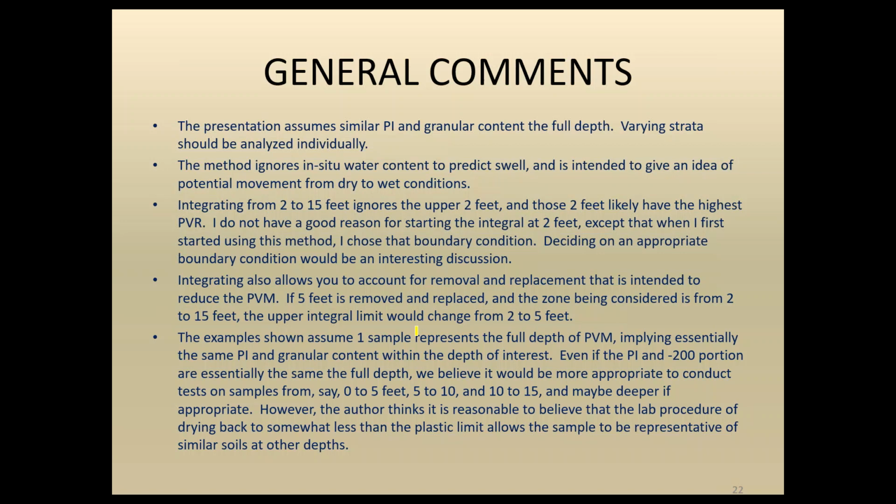So some general comments. We've, of course, assumed similar PI and granular content to full depth. So if you've got varying strata, they should be analyzed individually. The method ignores in situ water content to predict the swell, so it's intended to give an idea of potential movement from dry to wet conditions. Integrating from 2 to 15 feet ignores the upper 2 feet. And those 2 feet likely have the highest potential vertical movement, as I mentioned earlier.